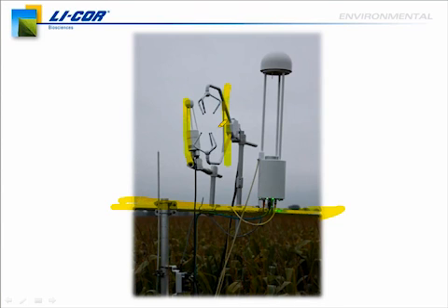And now here we've added a methane analyzer to the side, and we've got that analyzer positioned so that the sonic measuring point is near the center of the methane analyzer optical path. In this case, actually, the methane analyzer could have been closer to the sonic. We just didn't get them as closely positioned as we could have. But you want to make sure that you orient your instrumentation so that the air goes through the sonic first, and so that you minimize the perturbations to the prevailing winds as much as you can.